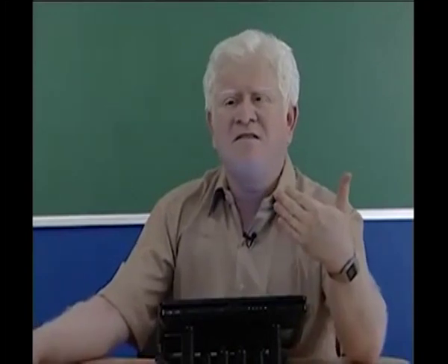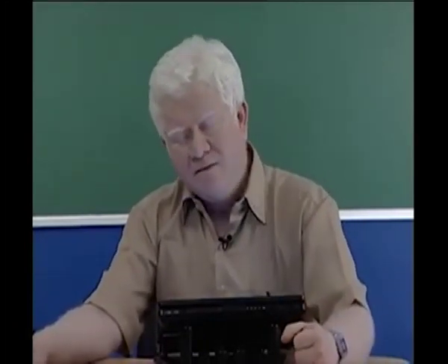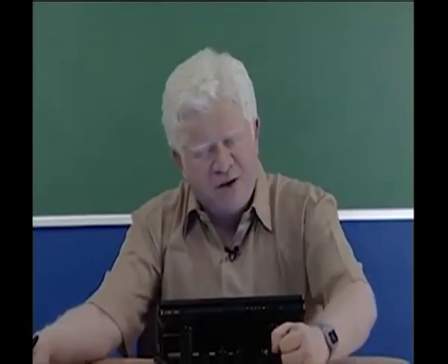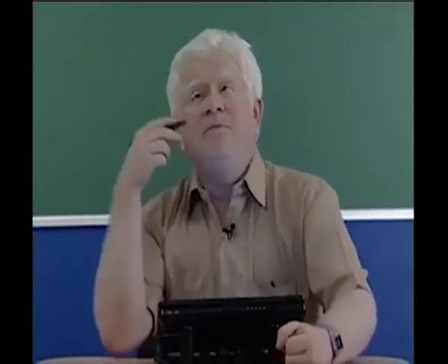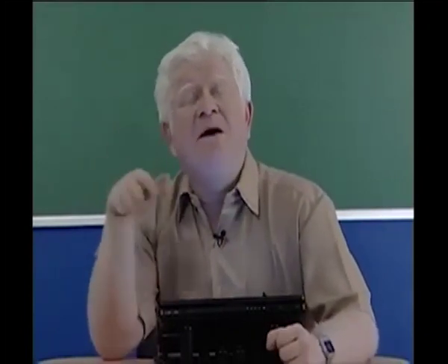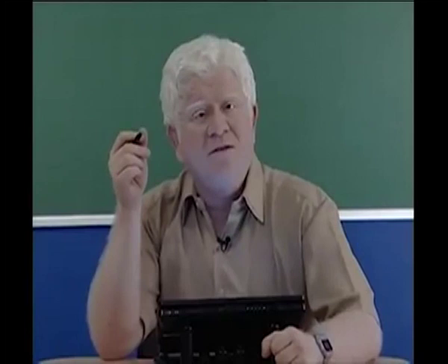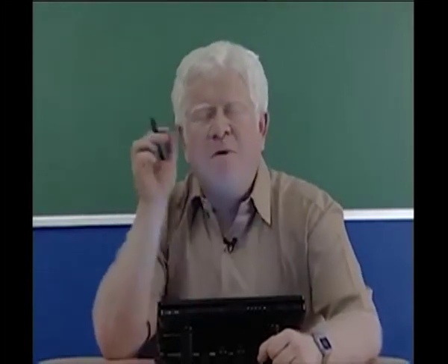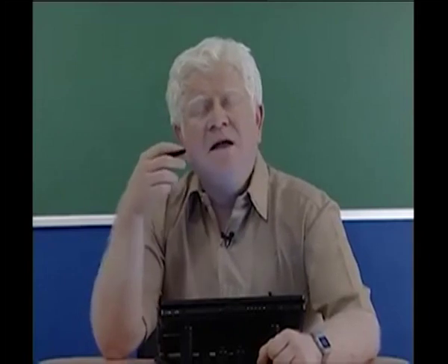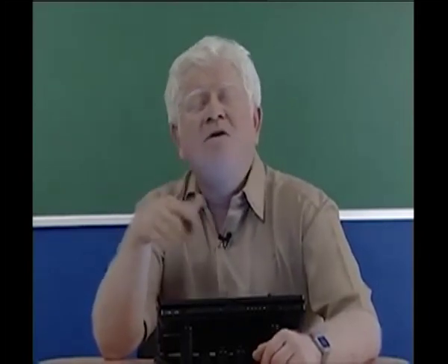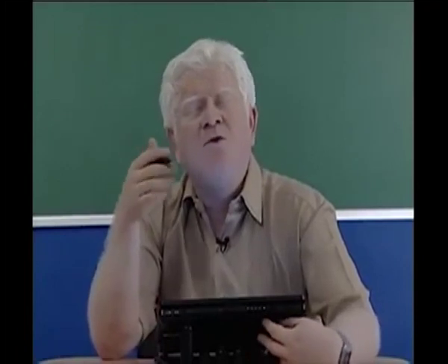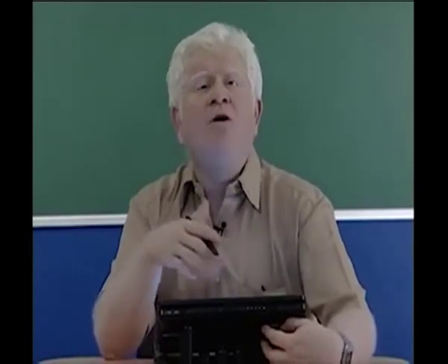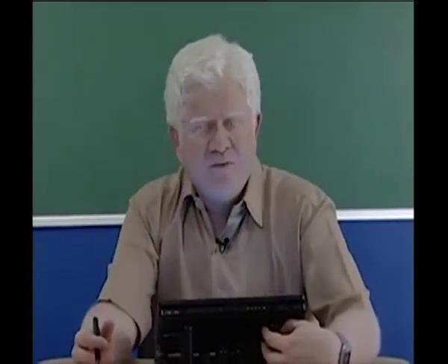But in the initial states, because we chose all the delay outputs to be equal to 0, the system has developed in this fashion. On the other hand, we could have set some initial conditions. We could have said that y minus 1 is equal to this, y minus 2 equals this, y minus 3 equals this. And if we look at the direct form 1 implementation, then we can clearly see how that system would take values of y minus 1, y minus 2 and so on as initial conditions and use them to contribute to the output right from y 0 to y 1 and so on.